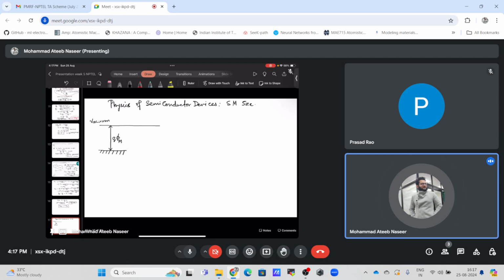And the semiconductor, let's say they are separated, they are far away from each other. Let's say this is my semiconductor, this is EC, this is the electron affinity, the semiconductor electron affinity. Now let me consider the n-type material. The Fermi level will be close to the conduction band, and the difference between the Fermi level and the conduction band is denoted by q phi n, and the valence band will be located somewhere below. This is the case when the metal work function is greater than the semiconductor work function, so basically phi m is greater than phi s.